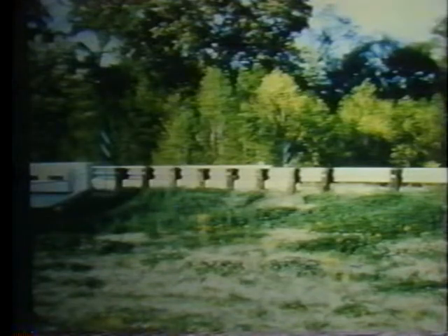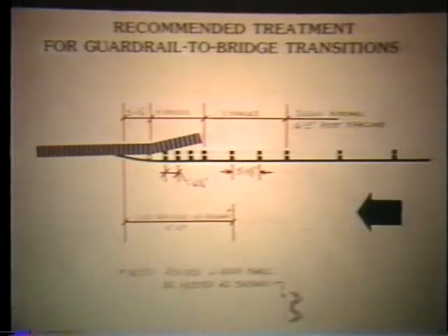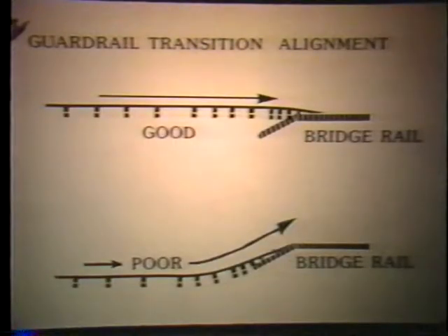concrete bridge rail. The Federal Highway Administration has developed an improved transition design to address the need for a high level of transition performance. The design includes W-beam barrier, C-section rub rail, barrier end anchorage, bridge rail functionally and structurally adequate, blocked out connection, and reduced post spacing.